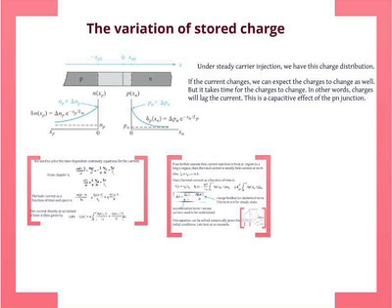The charges always have to take some time. They have to diffuse. They have to go away somehow, or they have to recombine. That takes time. It's not instantaneous, which means that the voltage will lag behind the current. This is nothing but a capacitor. Same thing happens in a capacitor. You have a charge stored, it needs to be discharged. It takes some time. Remember the RC time constant, all that stuff from your circuits, it's the exact same thing. The physics is different, but at the circuit level it's exactly the same.